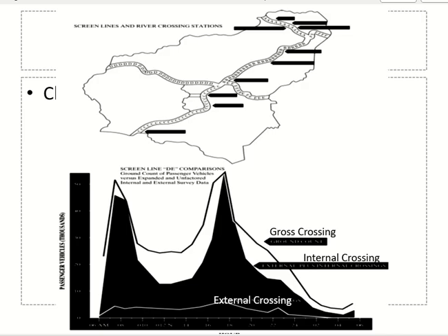But in a screenline count, because your area is small and you have only two zones, this possibility is very high. Somebody could be coming from here, just crossing, and going somewhere else. Because of the smaller area, you will have a lot of external crossings, so your data will have a significant number of external crossings as well. These are people who are from outside these two zones and are just crossing. Got it? Clear? This is the thing which you will not often find in origin destination.